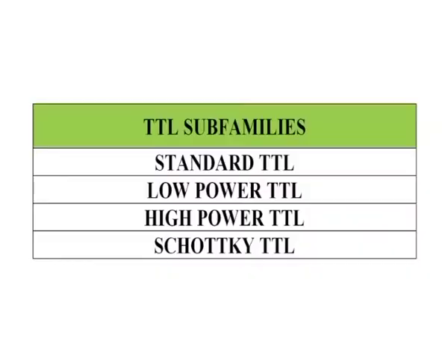TTL family of ICs. The original TTL series, referred to as the standard TTL series, was developed early in the 1960s. This series is still in use, even though its overall performance is inferior to the newer line of TTL devices such as the 74LS, 74ALS and 74F. The TTL family has a number of subfamilies including standard TTL, low power TTL, high power TTL, Schottky TTL.